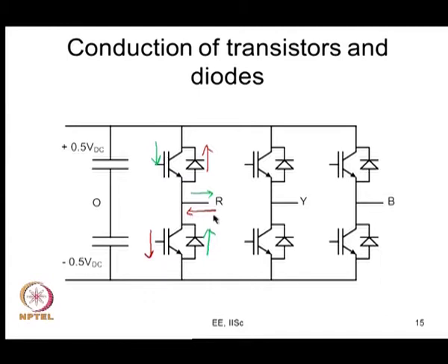Again, whenever you have current flowing in this direction and the bottom gating signal is high, then this transistor will conduct. Again, if the load current direction is like this and the bottom gating signal is low, the top diode will conduct. So, that is how the logic is. Here the active devices cannot conduct, otherwise. So, what is going to happen is the diodes conduct during the dead times. Now, in this direction of current, it is this diode that will conduct during the dead time.